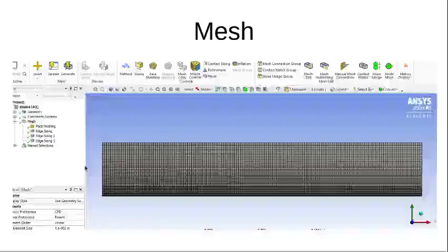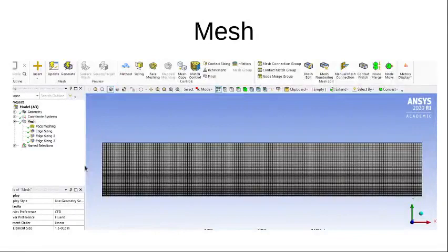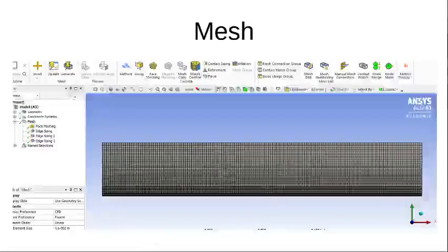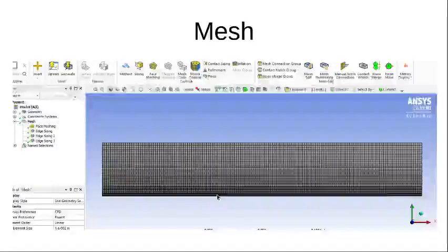And what I have tried to do is to discretize it in the form of a computational grid, which is shown here in this slide. So you can see that the domain is discretized into rectangular control volumes, and I have deliberately made the number of control volumes near the boundary to be substantially larger in density.